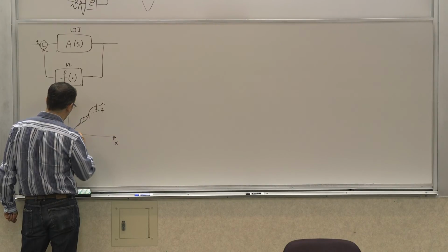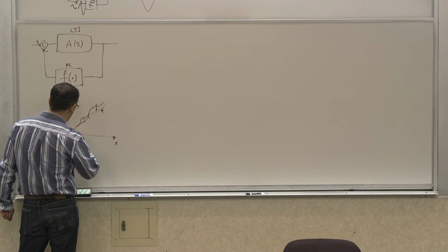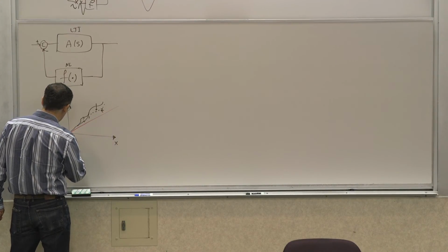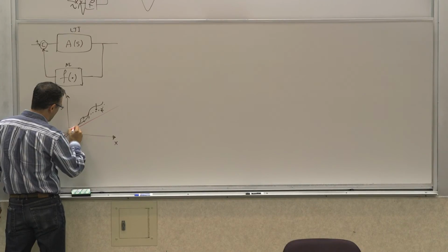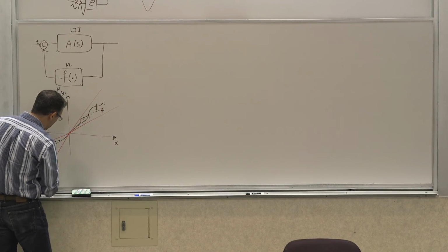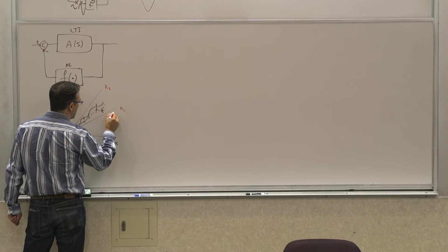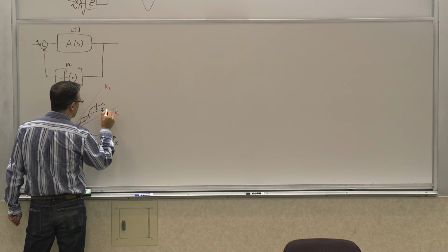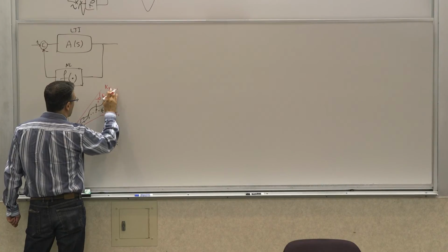But one constraint that we would like to apply to this is that no matter what happens over all times and all values and all the memories, it is constrained and confined. This curve is confined between two lines with two different slopes, let's say k1 and k2. This one has slope k1, k1 over 1, and this is the slope of k2, k2 over 1.